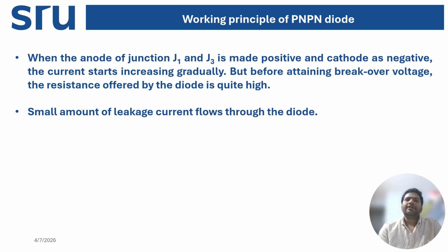Next is the regenerative action. Using the two transistor analogy, one PNP and the other NPN transistor, internally connected, which was already explained in the previous slide, the current of one transistor is amplified by the other transistor. This creates a positive feedback, leading